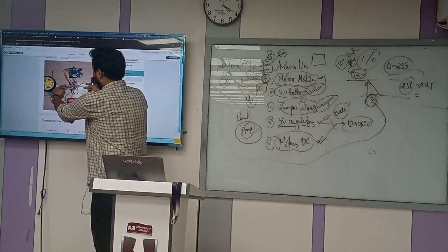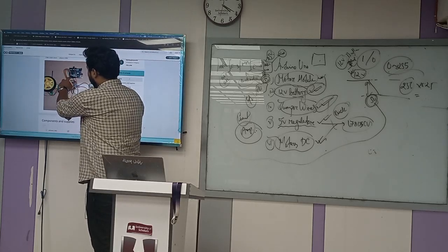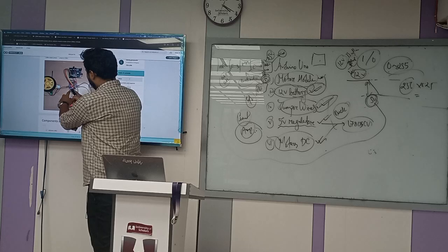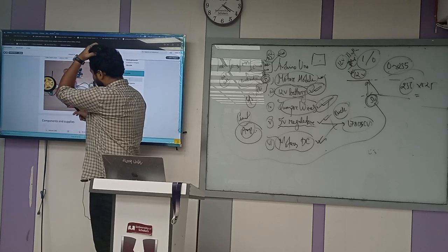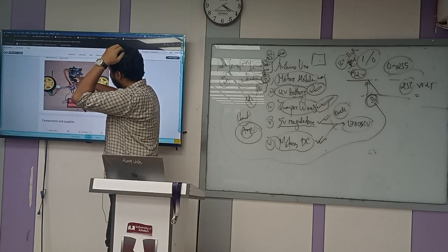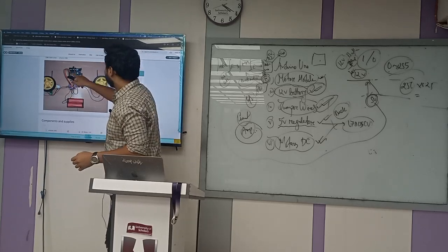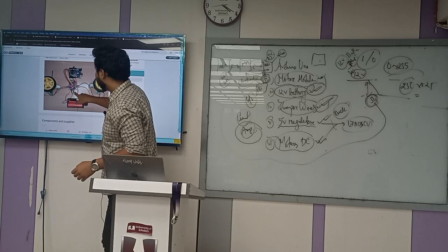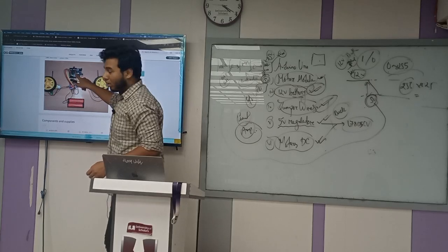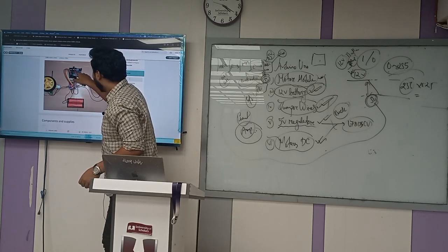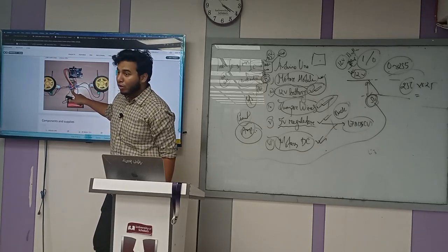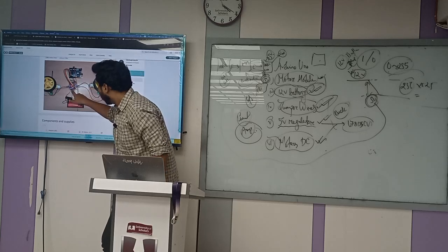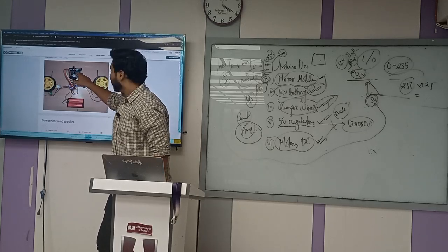You have 2 motors, 2 outputs, 4 PWM pins over there, a 4 pin connection, and 2 connections for the battery and the ground. Okay, and to complete the connection, there is another ground and 5 volt considered with the motor module, because this Arduino is powered by the motor module. Why? Because the 5 volt is output. So you can connect the battery with this and connect the motor module as well with this Arduino.